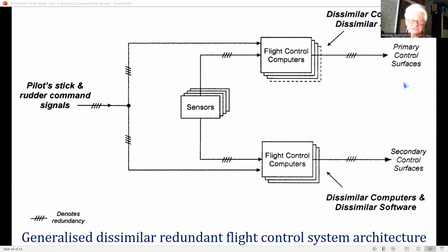flight control system architecture. Modern airliner design practice is to split the basic control surfaces into two or three sections, with each section controlled independently by its own actuator. The movements exerted by each section of the control surface are thus sound aerodynamically, and the failure of an individual section can be tolerated. This gives increased failure survivability to the flight control system. Most of the control surfaces are controlled by two actuators, in some cases dissimilar types of actuators.